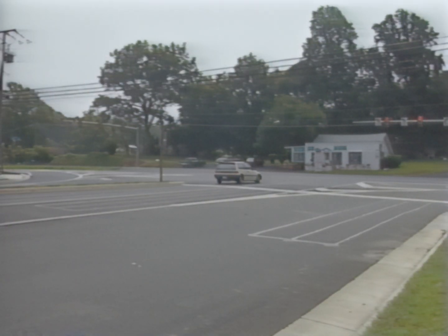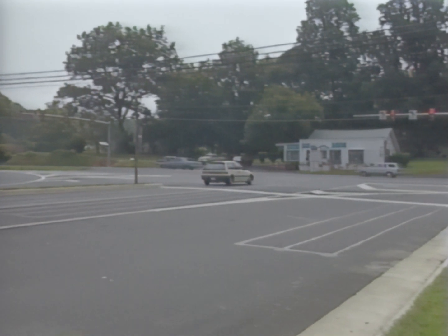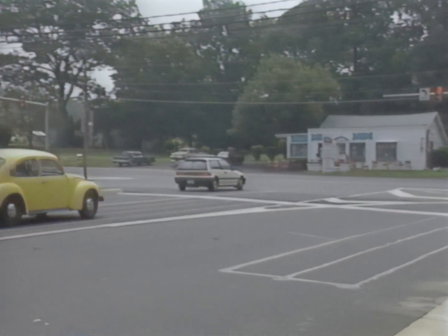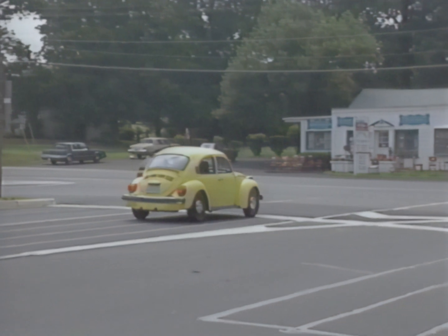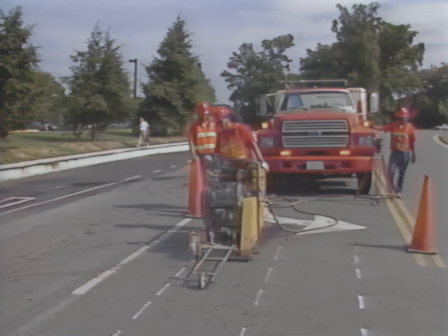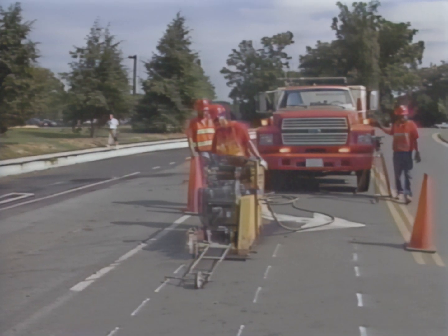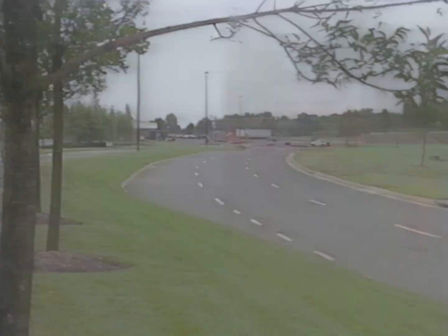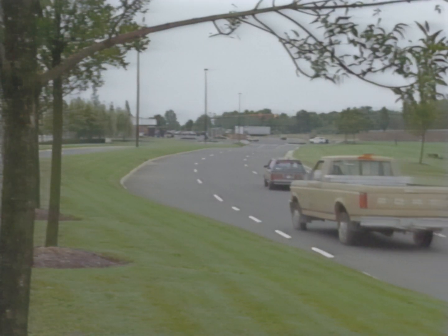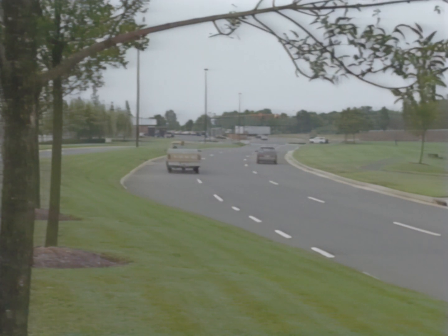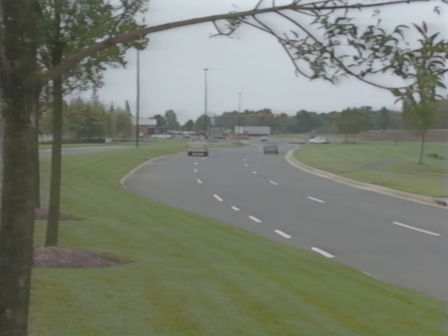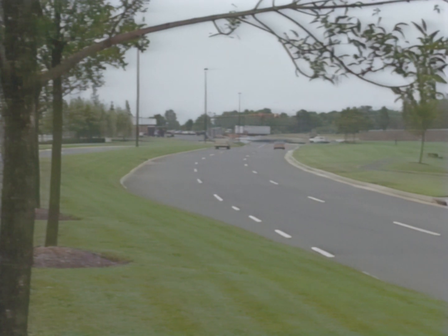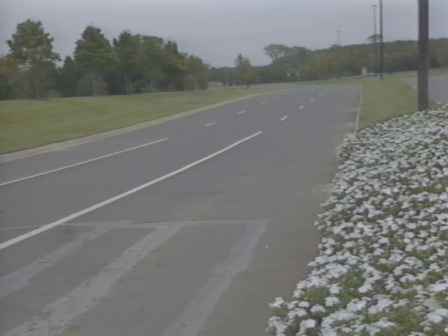Occasionally, drivers who have proceeded past the stop line to wait unsuccessfully for a gap in the traffic will be stranded. The controller may skip the turn arrow in the next cycle because it cannot sense a vehicle past the detector. To prevent this situation, some agencies extend the loop 1 to 6 feet beyond the stop line. Also, when the left turn demand requires 150 feet or more of storage space, or when higher approach speeds require longer deceleration lanes, the left turn lane layout should include an advanced detection loop.